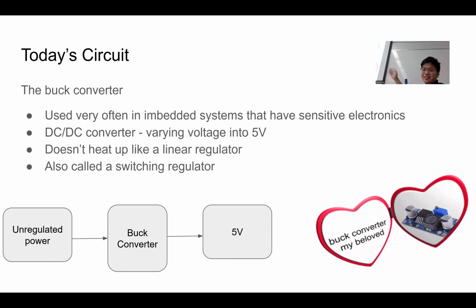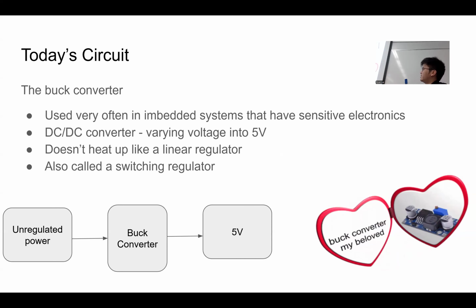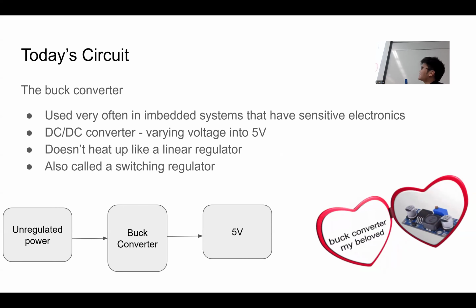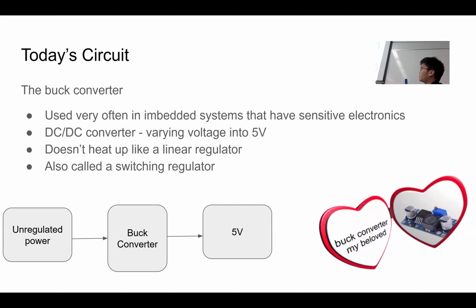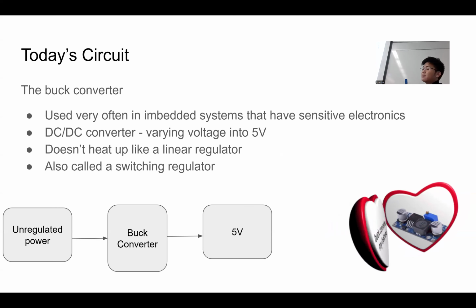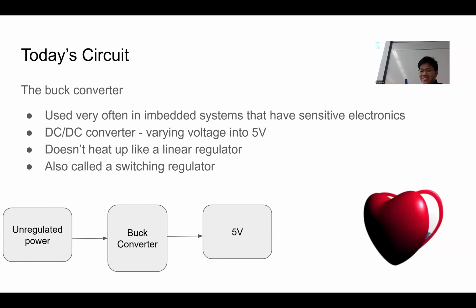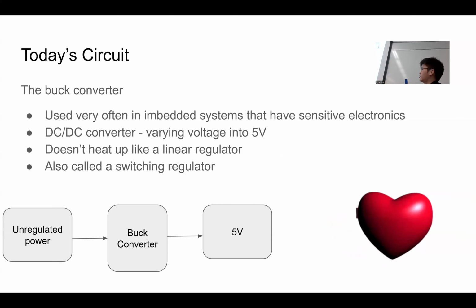And you'll have like 5 or 10 of these in one thing just to set all the different voltages, just to power all your different electronic components. And the nice thing, if you are familiar with these kind of converters, is they don't heat up like linear regulators. Linear regulators do the same thing, except they burn that power as heat. And what ends up happening is you waste a lot of energy, and also you get a very hot component depending on how much current you're drawing.